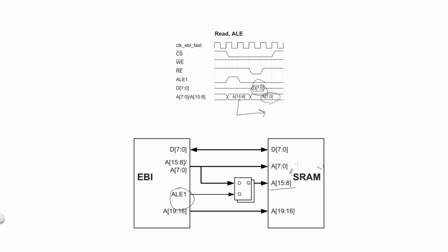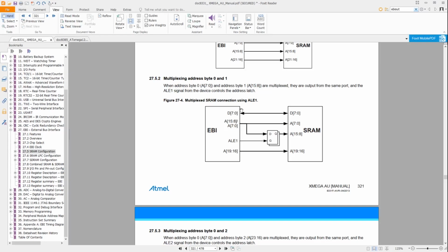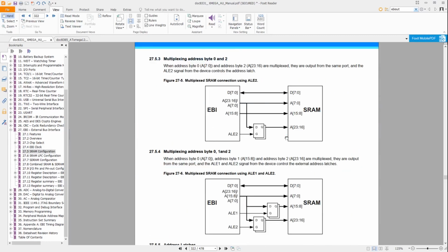The main difference when used with other devices is that the address lines may not always be connected to the external entities, such as with I/O ports. Some devices are very simple and just need an enable signal and the data bus. Although this arrangement is the one we will actively be using in the course, you are also responsible for understanding the other arrangements available for the purposes of the exams.